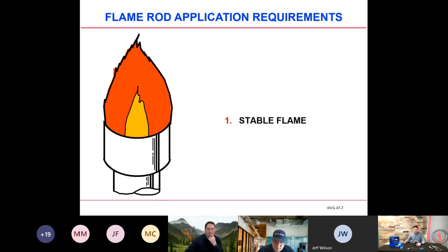So the one thing you might want to consider, if you're not getting a good flame strength, either using or measuring by your DC microamp meter or your flame relay display, would be turning back the pressure on your pilot or the main gas in order to let that flame actually sit back inside of that nozzle, making a really good earth ground connection.